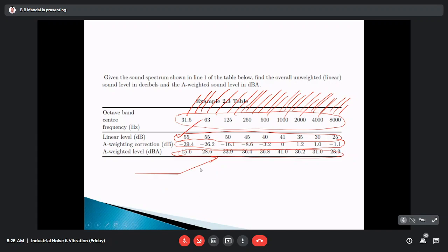If I use a Z network, then whatever you are giving in the linear level will be directly passed. This is basically bypassing the network. And what we actually do is try to make a band pass filter. I have said that 20 hertz to 20 kilohertz is our range of interest.